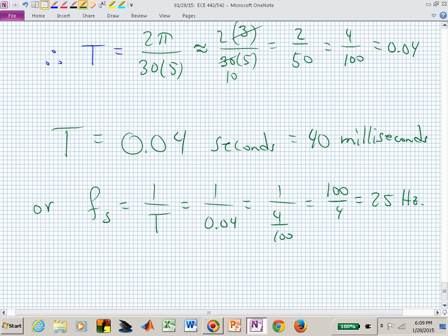So now what's the advantage? The question was, what's the advantage of having 30 oscillations, or 30 samples per oscillation? Is that what the question was? Now you've possibly heard of the Nyquist frequency. Have you not? And what's the Nyquist? Double. So you say, oh, I want to sample at twice the highest frequency. That's so you can preserve the information content.